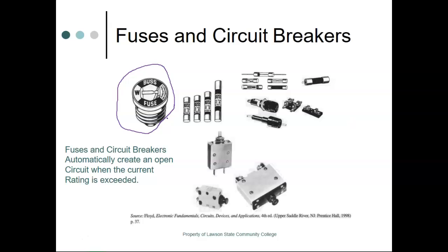Then what you generally will see in things like meters and other electronic devices are these fuses right here. They come in several different ways, because the interesting thing about fuses is they have all sorts of different functions. So let's say you're trying to start a motor. Well, when that motor first engages, it's going to suck up a lot of current trying to jump itself.